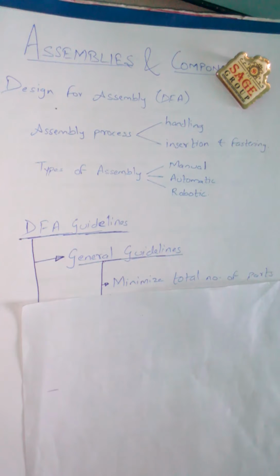The first is that the part must exhibit motion relative to another part that is declared essential. The second is that there is a fundamental reason that the part is made from a material different from all other parts. The next is that it would not be possible to assemble or disassemble the other parts unless this part is separate, that is, it is an essential connection between the parts.